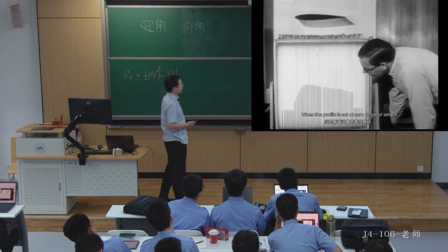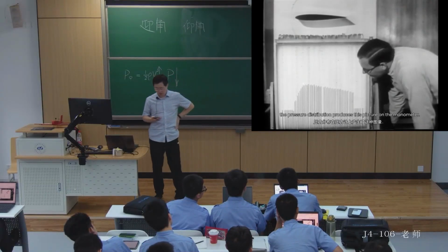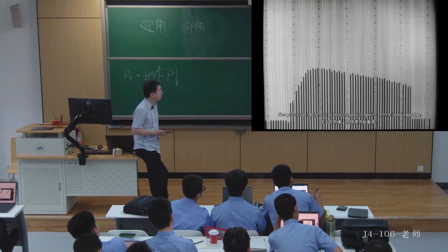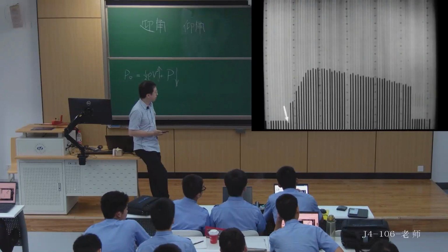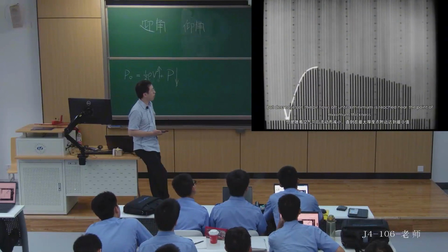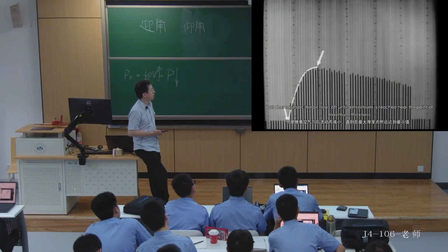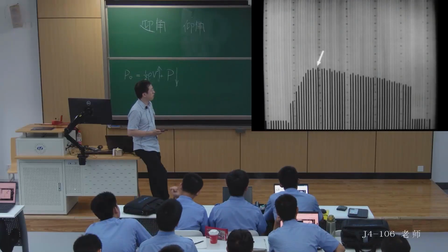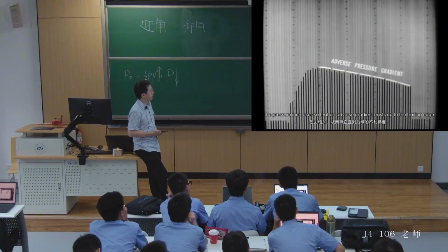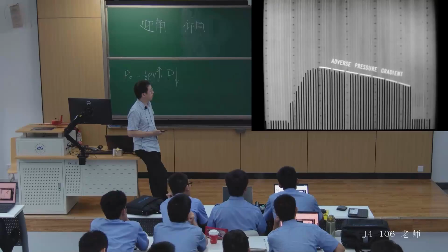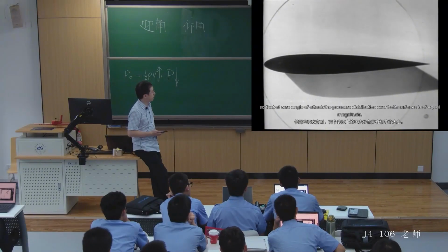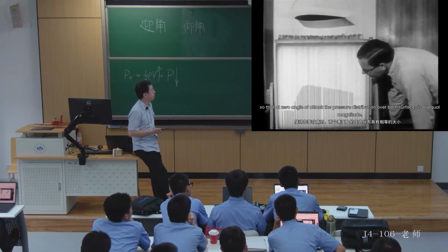When the airfoil is set at zero angle of attack, the pressure distribution creates this pattern on a single surface. The highest pressure appears at the leading edge, but it decreases as the airflow continues, and minimum pressure is reached near the thickest point. After this point, the pressure increases, creating an adverse pressure gradient all the way to the trailing edge. The airfoil is shaped so that at zero angle of attack, the pressure distribution on both surfaces is equal in magnitude.